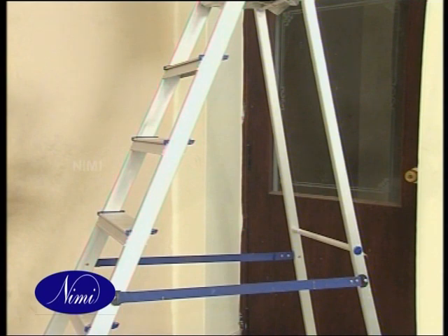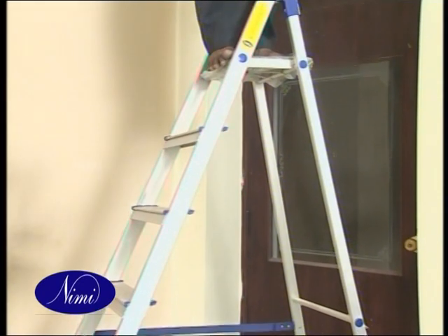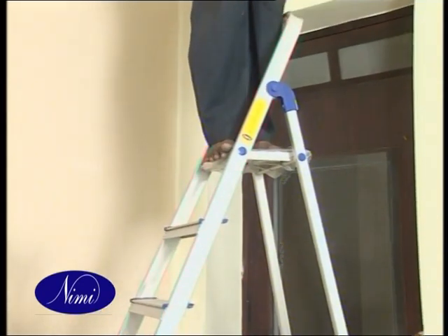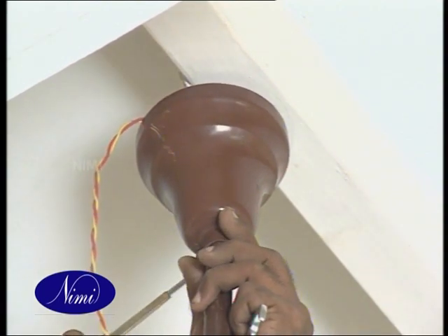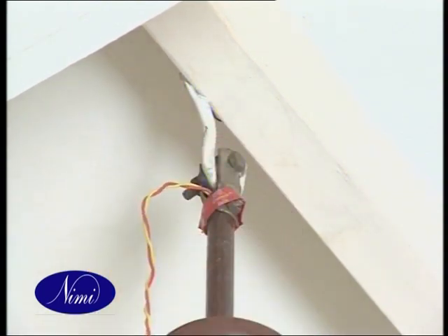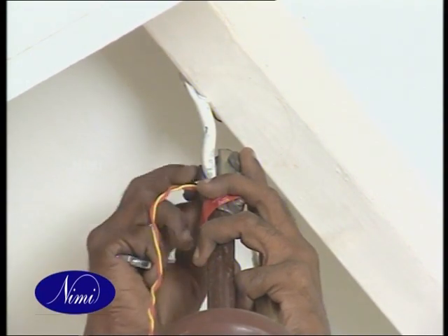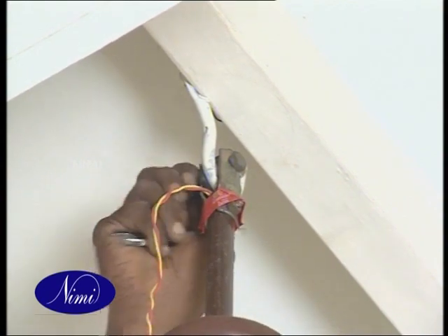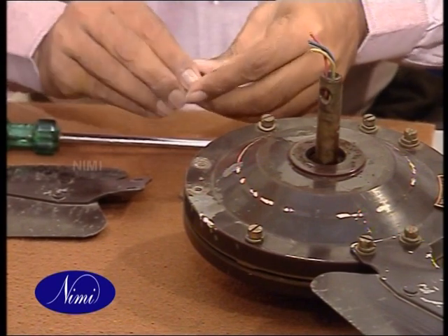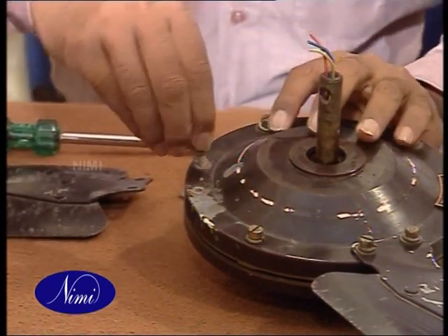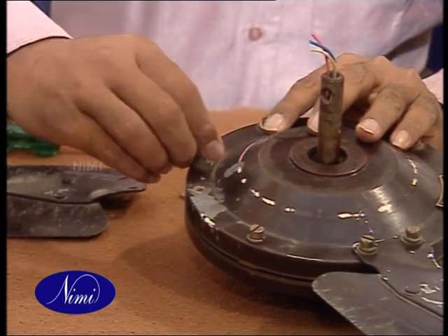Make arrangements to reach the ceiling fan through the stable means of elevation. Safety of the worker is of utmost importance. Disconnect the wires from the ceiling rose. Lower the top canopy. Bring down the fan after removing the split pin, the cotter, and the rubber grommet from the shackle and clamp. Remove the fan blades and refit the screws along with the spring washers in the body of the fan itself so that you may have easy access to them when refitting.